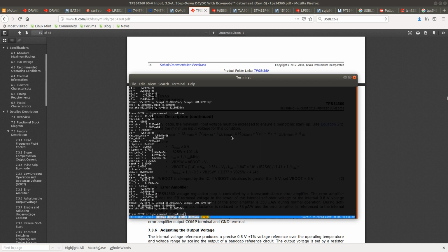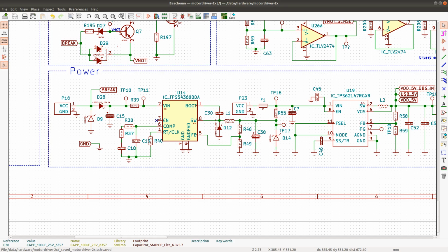So in this case, this is going to be fine because this regulator can accept up to 17 volts on its input. So if this goes up to 14 volts, nothing is going to break here. But it's also important to make sure that anything that is connected here can accept voltages of 14 volts.